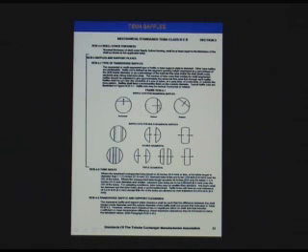This would be a vertical cut where the fluid flow basically is going side by side. This is an angular cut. We haven't used those, and I'm not familiar with one that we've used. This is double segmental, where the flow basically goes back and forth, but the flow pattern has an intermediate baffle here, and this is typically used when you want to minimize pressure drop.